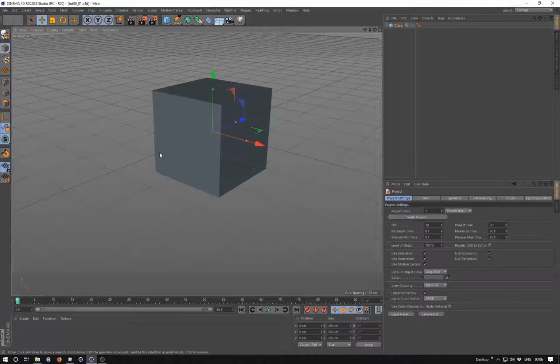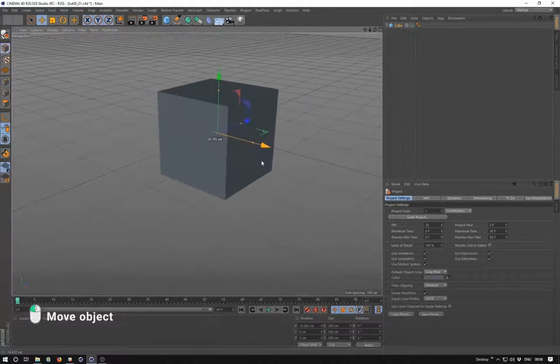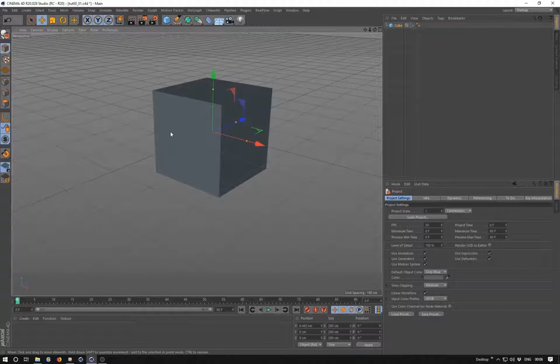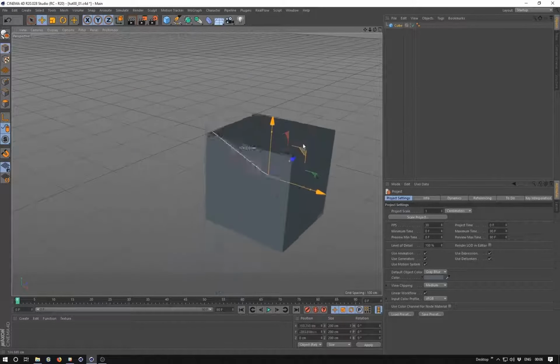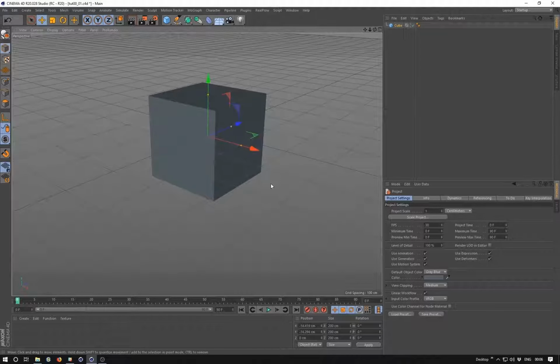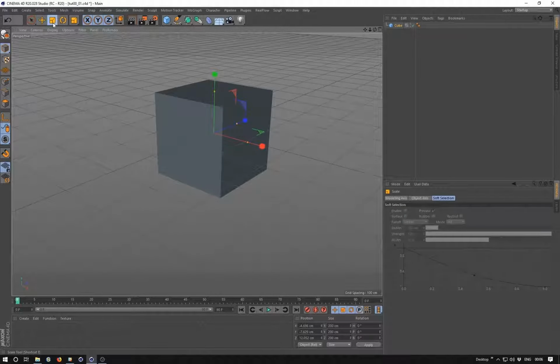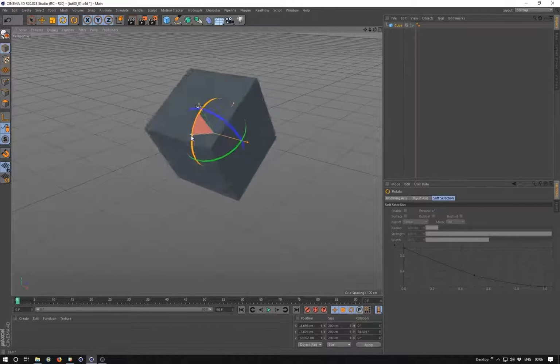To move an object along the red axis, you just have to hover over it. It's highlighted now. Press and hold the left mouse button and drag. If we want to move an object on a surface, we use one of these corners. When we do so, the axis along which we're able to move our object will be highlighted. If we don't care about moving it along axis, we can just click on the object and drag it. Instruments of rotation and zoom work in the same manner.